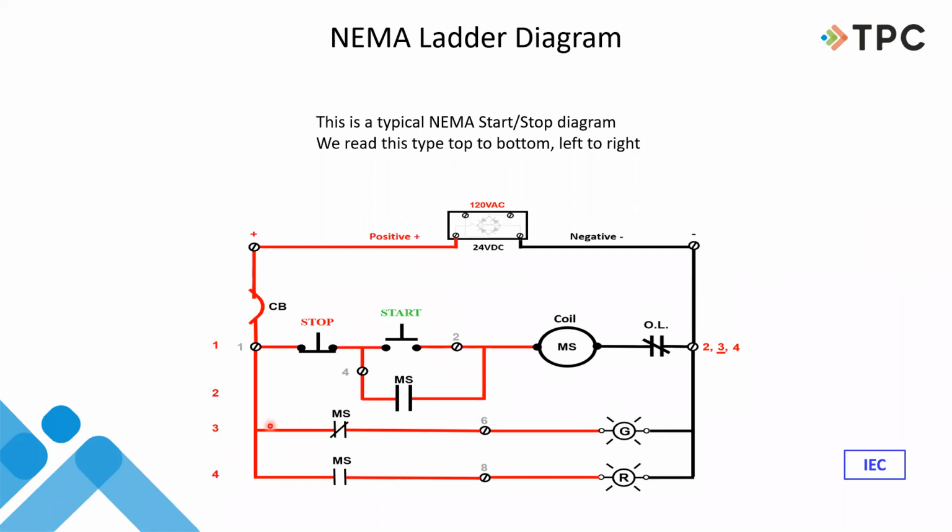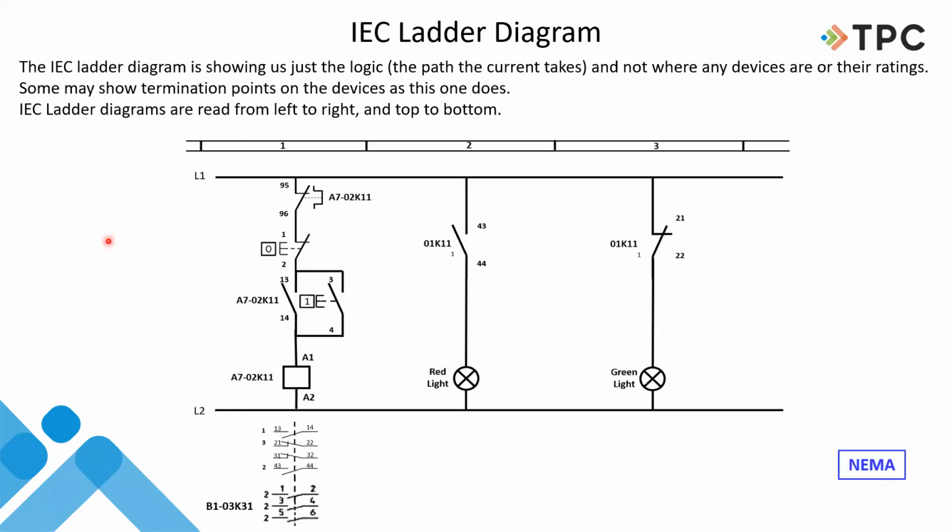So these are probably symbols you're more used to seeing than IEC, but we're going to show you that these basically work the same. IEC works basically the same, just looks different. So going from this stop-start station with a couple of pilot lights and a holding circuit, we're going to an IEC drawing that has the exact same thing. Exact same thing, just drawn differently and somewhat confusing at times.